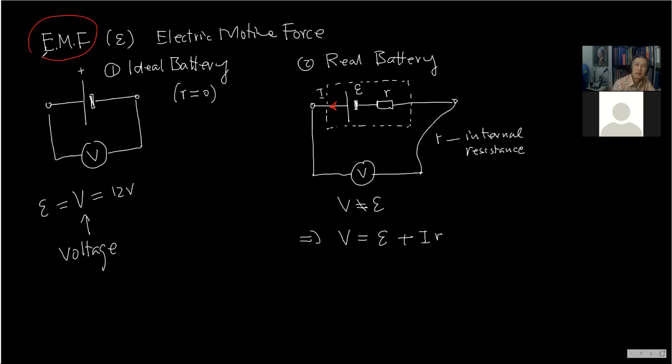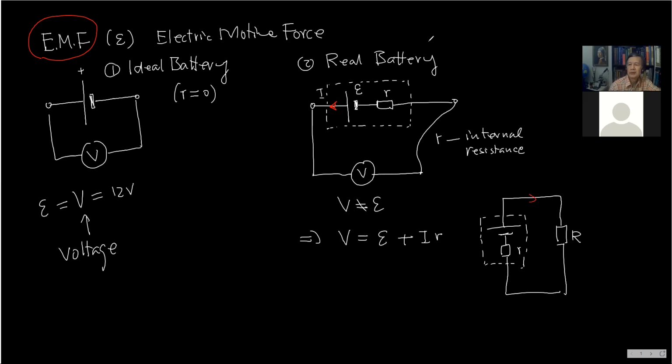Is that relevant to your question? Yes. That is why we have to be careful when we're dealing with Ohm's law. We have to ask whether this battery is ideal or real, right? Don't worry, they will tell you. For example, when we have a problem, they will mention if the battery has an internal resistance. If they do, then you just draw another resistor here, realizing this is just part of the real battery. I still use a small r for internal, and a capital R for the external resistor. Otherwise, we still can apply Ohm's law. Is that your concern?